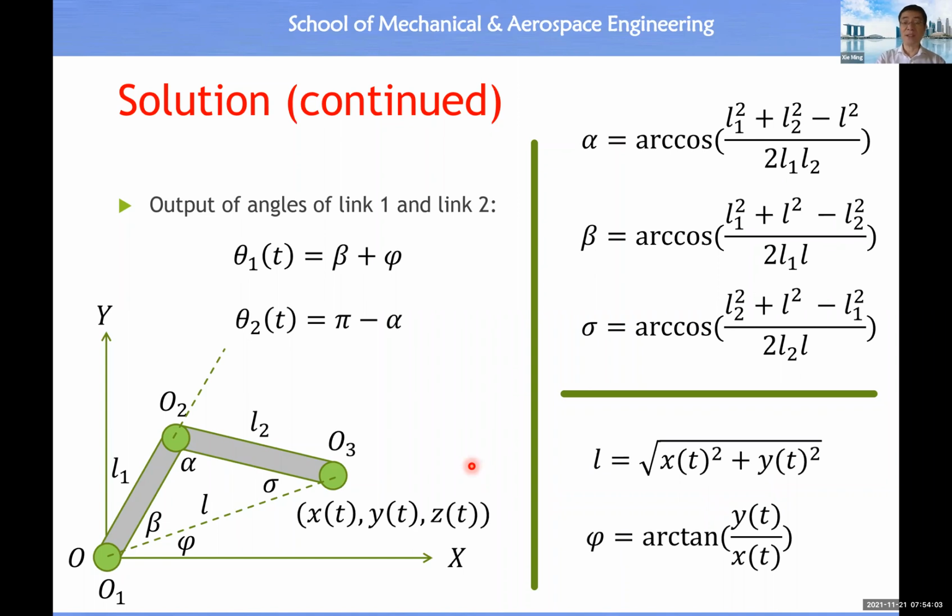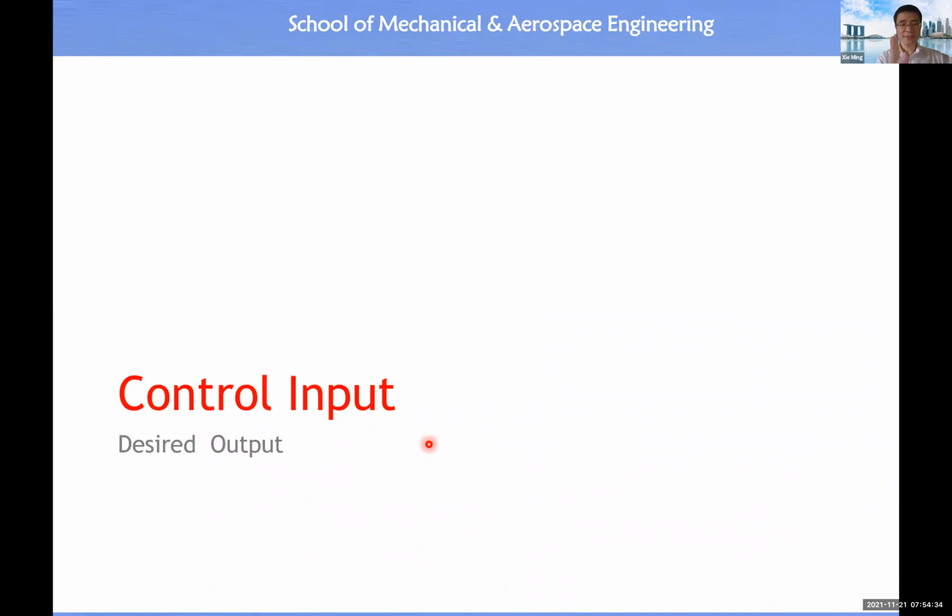So you see, we have the full set of equations for us to determine the input motion to this robot mechanism from the knowledge about the output motion, right? So this is a typical scenario of making use of inverse kinematics to determine the value in joint space from the knowledge of coordinates in task space, all right? So now you understand what is joint space, all right?